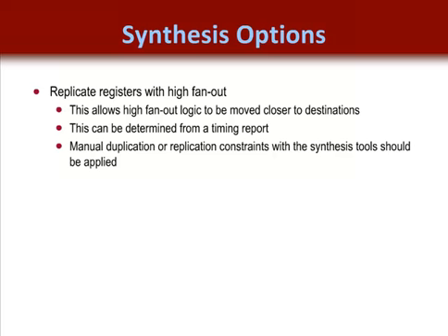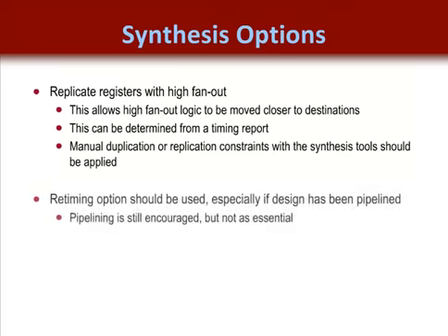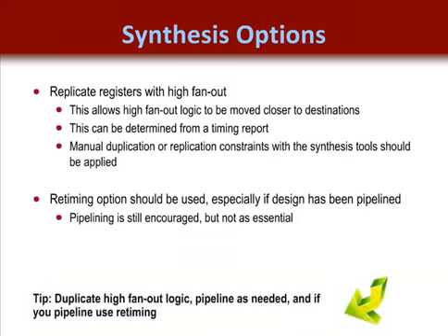This will require you to prevent the synthesis tool from removing the extra logic, which is the default behavior of the synthesis tool. And this is done by using what is called a keep attribute. If your synthesis tool allows you to control the replication, that can also be useful. But keep in mind that replicating logic just once is rarely sufficient. Depending on how far from meeting your timing needs you will probably have to replicate that logic a few times. Once you have added registers through pipeline stages, you should also remember to allow your synthesis tool to migrate those registers where they're needed. This is done with the retiming option.